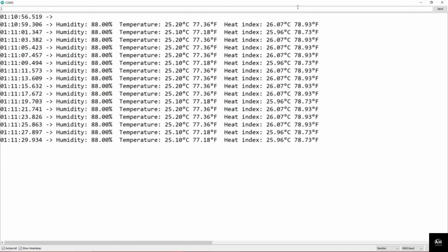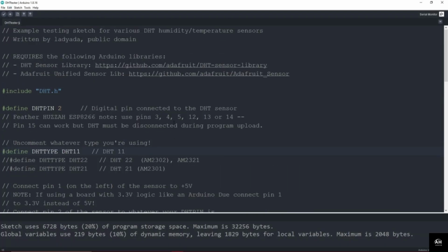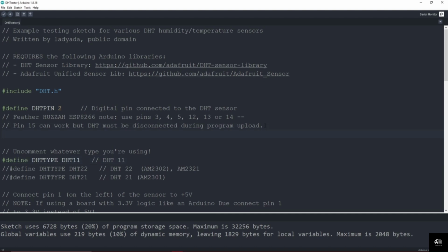So now what we will do is close this serial monitor, and come here where we have defined the pins. In here we are going to define int relay 1, which will be equal to pin 12, because we have connected our relay module with pin 12, which is connected with our smart socket.